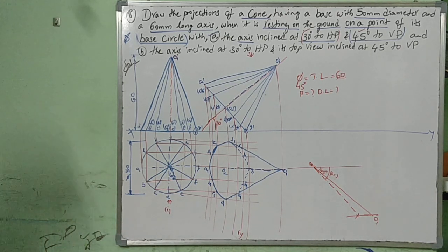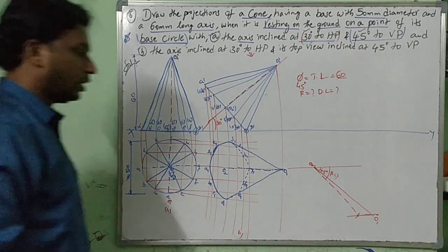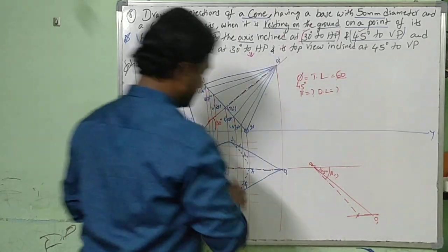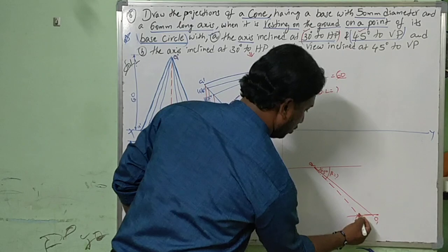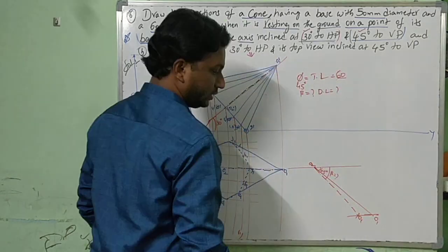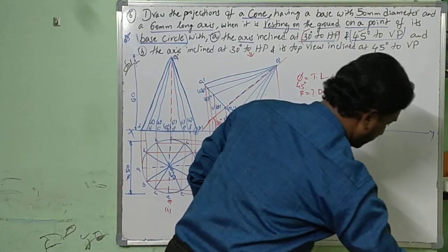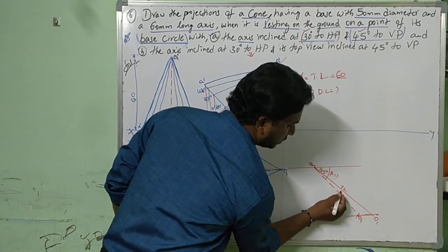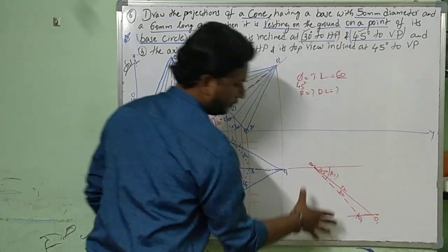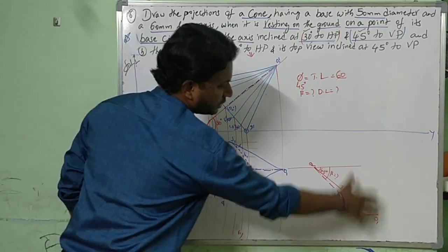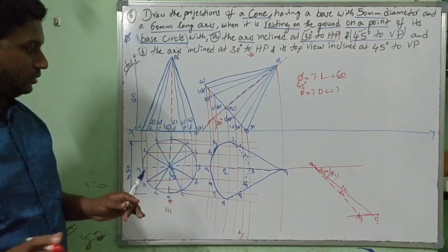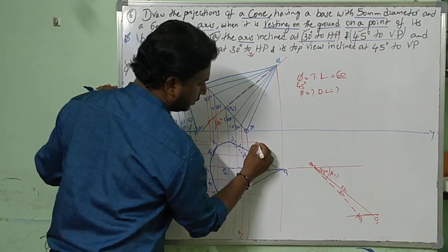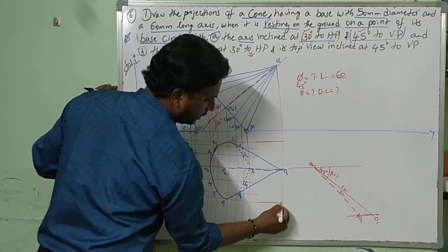Hope you all understand this. Right? Now the problem is, this has to be rotated with respect to this O2, O1. You may get confused. Just treat this as true length, treat this as diminishing length. Now with respect to O2, O1, whatever is here, we are supposed to reconstruct it, right? That's by which method? Box method. Now I have not completed the box here. Try to extend this line. Now this becomes the box.